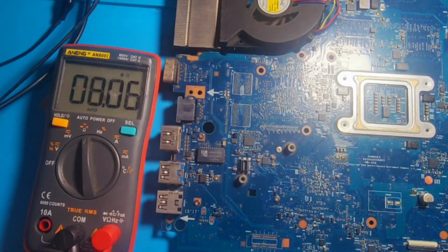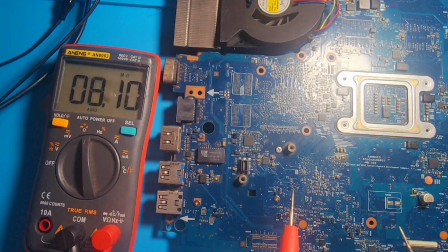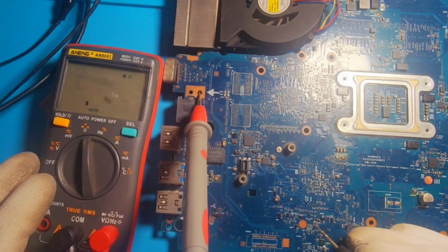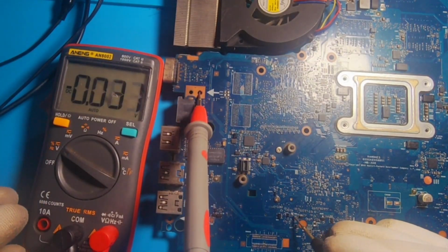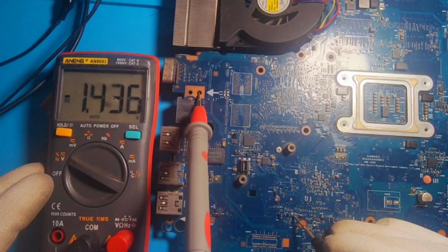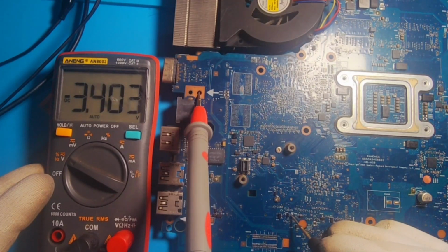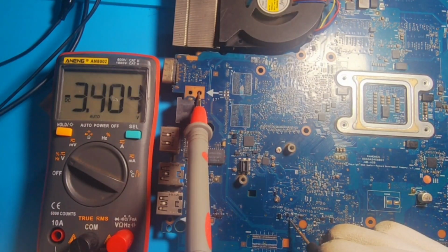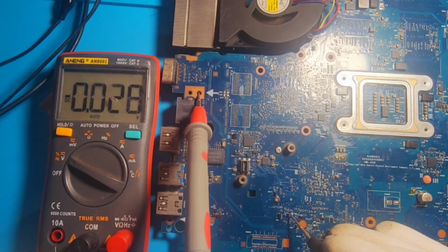Okay, now I have plugged in and the board turned on. So let me see the voltage. On one side, I'm getting 1.4 volt. On the other side, I am getting 3.3 volt. This is the pull-up voltage for this resistor, and on the other side we are getting 3.4 volt and 1.5 volt. So the data line is having a problem, the 3.3 volt is not stable there.